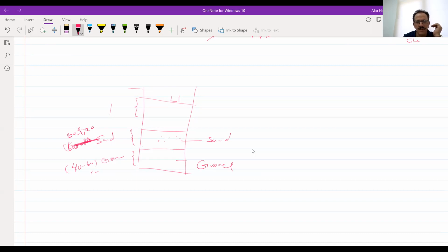As the first thing we need to know, when we are going to design this tank, this filter, like a sedimentation tank, we should have more than one filter. For example, if this is a filter, we should have another filter here.